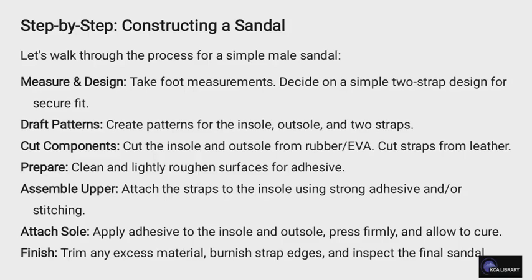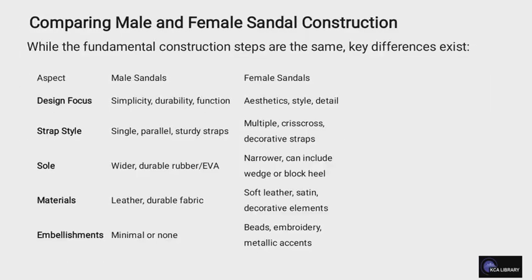The next is assembling the upper, which is to attach the strap to the insole using strong adhesive or stitching. The next is attaching the sole: apply adhesive to the insole, press firmly, and allow to cure. The last one is finish, which is to trim any excess material, burnish strap edges, and also inspect the final sandal.